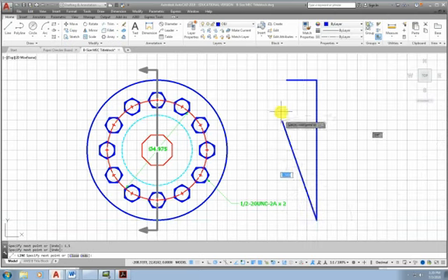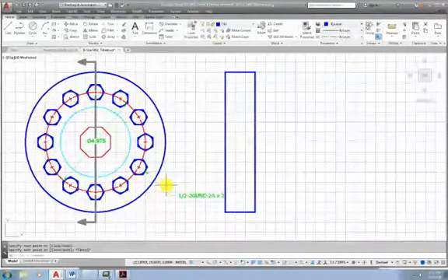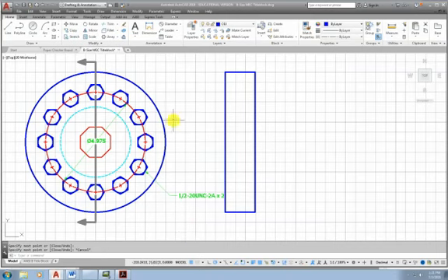And then we'll go over this way. Again, it's called swiping, and this is called direct distance, where it allows you to use the computer rather than having to re-input the dimensions all the time. It's a little bit close, and so I'm going to move it over just slightly.